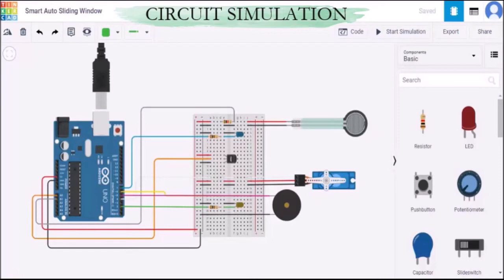In our project, we are using Arduino Uno R3, small breadboard, force sensor, temperature sensor, micro servo, piezo, 3 resistors, and 2 different colors of LED, which are the blue LED and yellow LED. The function of the resistor in this circuit is to reduce current flow so that the LED will not blow up. Also, the reason why we use different colors of wire is that it is easier to inspect if any component has a problem. So, how does the circuit work?